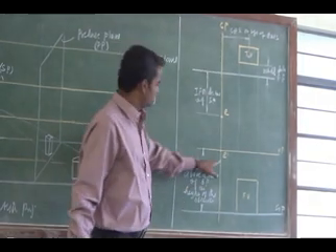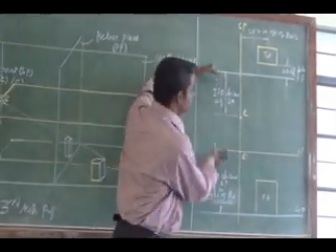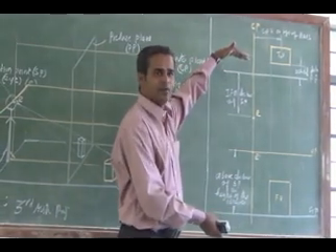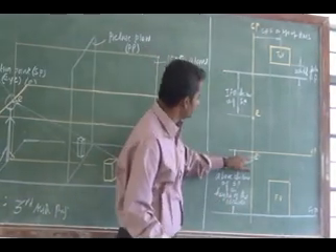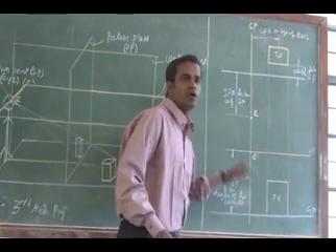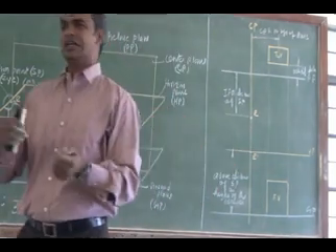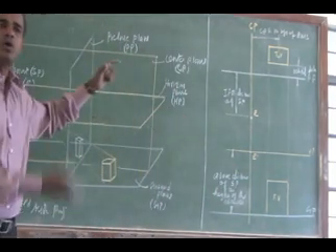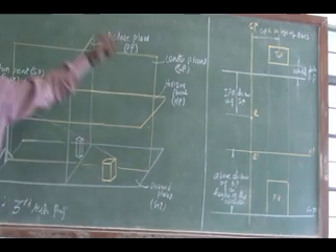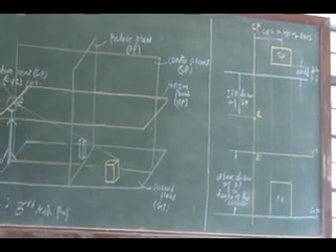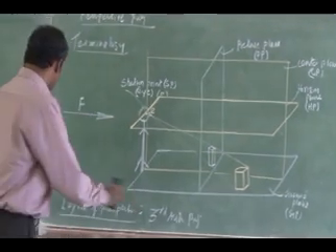Why? Otherwise, if you have a reduced gap, a lesser gap from picture plane to ground plane, E has to go above, or E will come below. So you will have a little bit of confusion. To avoid that, you keep a sufficient gap between the picture plane and the ground plane.